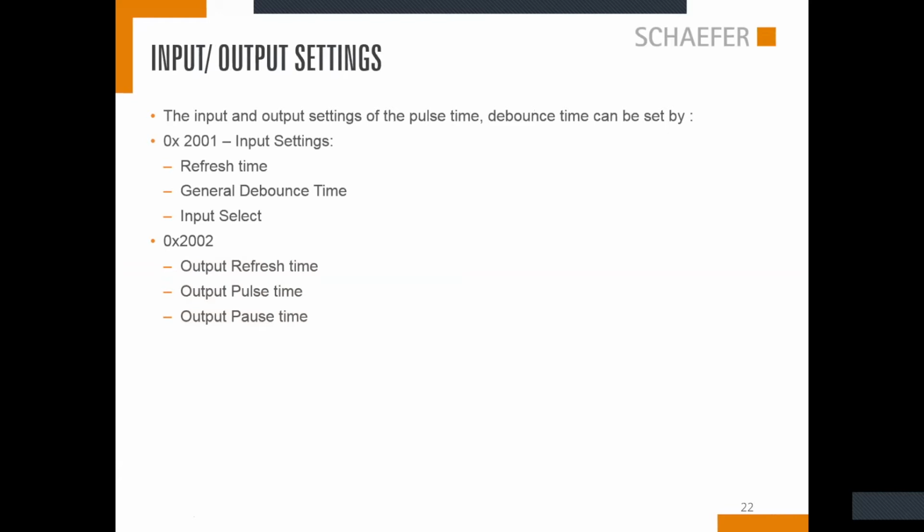So the input and the output settings can be controlled. The reason behind this is that by design, all our input and output pins are tied to the same pin of the microcontroller. That means each IO pin can be used as either an input or an output. This is done based on a pulsating system where, even though this pin is high, meaning the LED of the button is lit, if the customer presses this button, a message is still sent to the lift controller to show that this button has been pressed again.